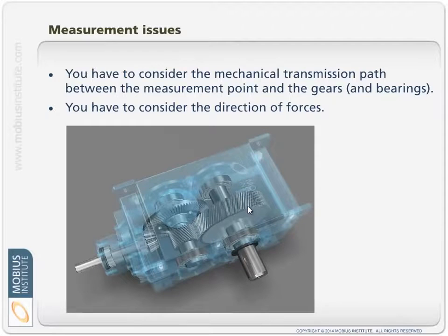I mentioned this briefly before, but in the case of bearings, for example, the bearing is generally at a location where you can place an accelerometer, and there are all sorts of issues regarding monitoring of the bearings, trying to get as close as you can to the load zone, considering the design, what's the thrust versus radial components, and taking the measurements correctly.